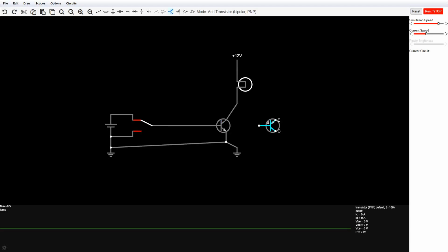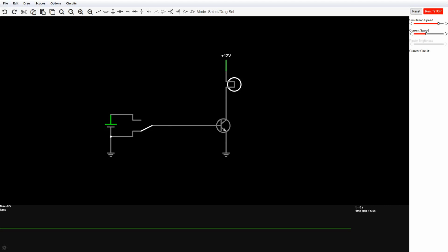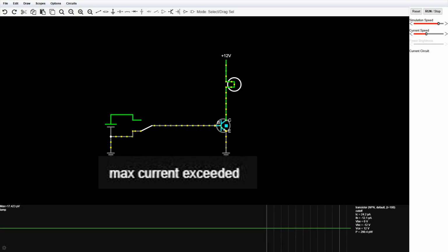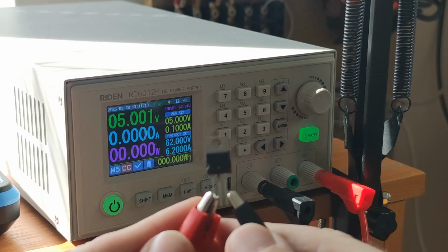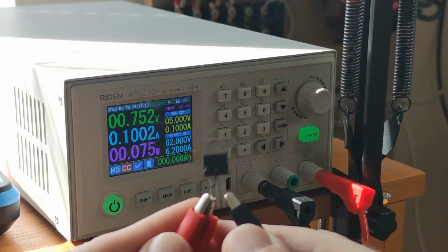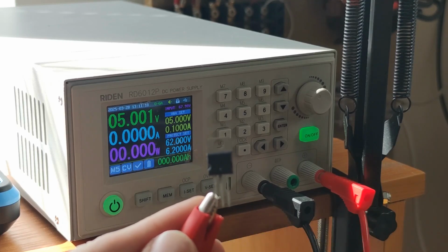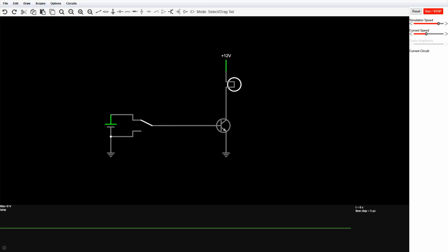I'm using an NPN transistor. PNP works the same, but with reversed polarity. Plus becomes minus and vice versa. The base-emitter junction behaves like a diode. It will consume all current and wants more and more, and the voltage between base and emitter won't rise above 0.7 volts, while we want to apply an astonishing 5 volts. But no worries, one humble resistor saves the day, dropping that wild voltage down for a safe 0.7 volts.